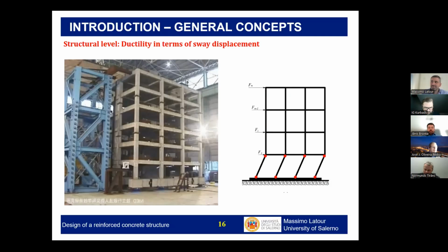So the way I see that they can be used more efficiently in seismic zones is to accept the flat slabs, but anyway, consider some beams on the perimeter of each floor. And so you try to have the frames, which are classical beam-column frames, and still use the flat slabs in the inner side of each floor, accepting that these won't work so well for the horizontal forces created by the seismic event.